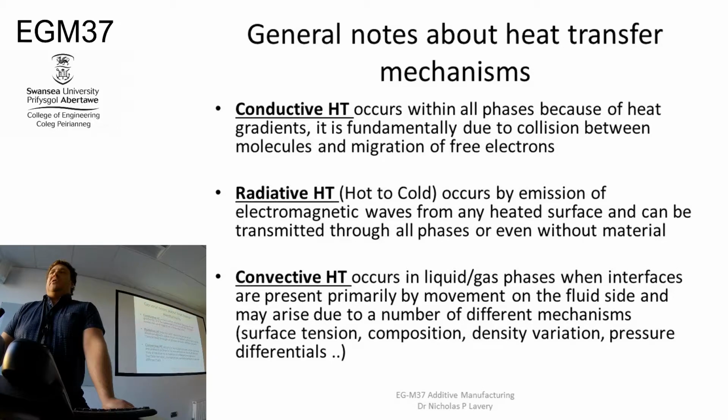So just to make sure that we all know what we're talking about, conduction occurs within all phases, be it liquid or solid or gas, because of heat gradients, and is fundamentally due to the collision between molecules and the migration of free electrons. That's conduction. Radiation occurs by emission of electromagnetic waves from any heated surface and can be transmitted through all phases, or even without material. So even if you're in a vacuum, you can get radiation heat transfer.